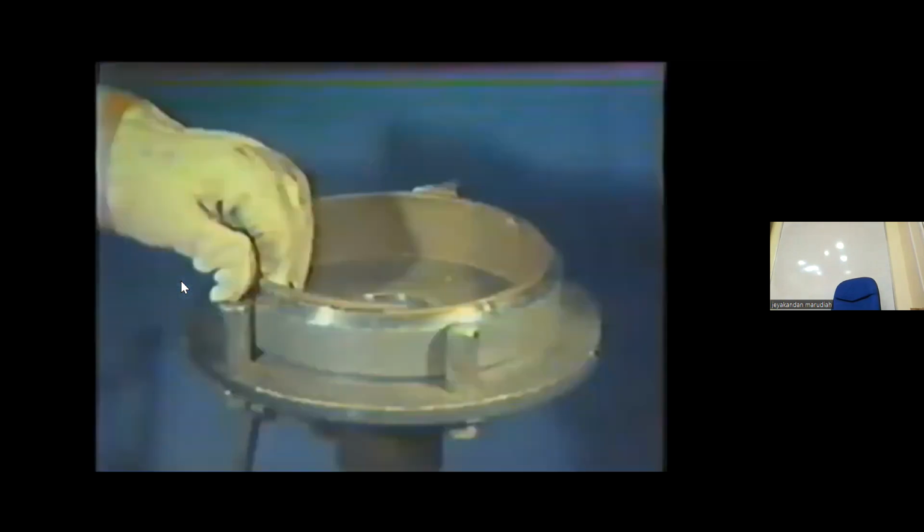Start the arc on the bevel and melt a small portion of the bevel into the insert. Deposit tack welds every 1.5 to 2 inches until the overlapped portion of the insert prevents good fit up. A hacksaw or hand shears are used to cut the overlapped portion of the insert.